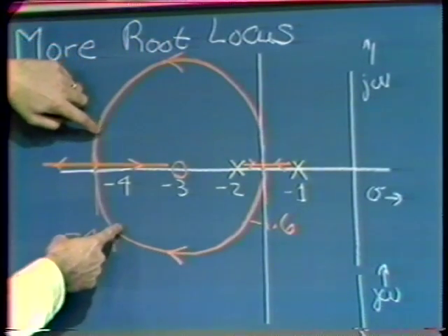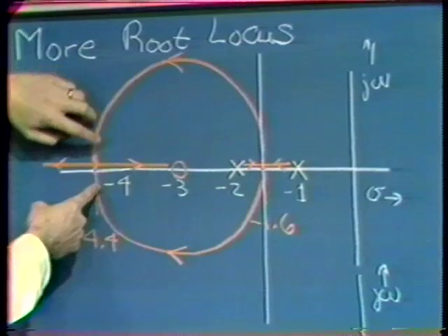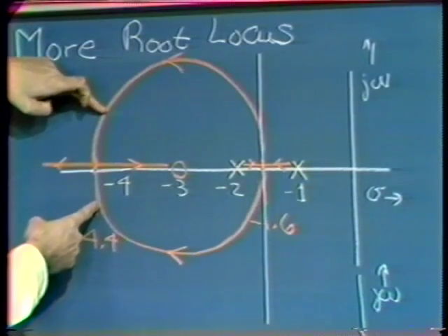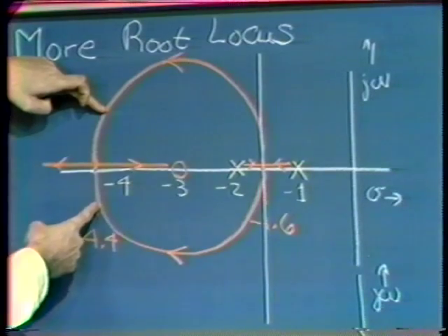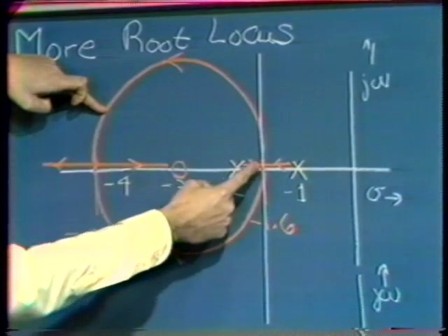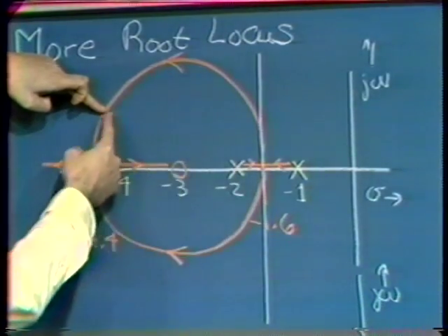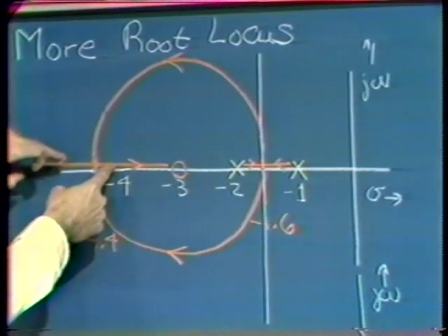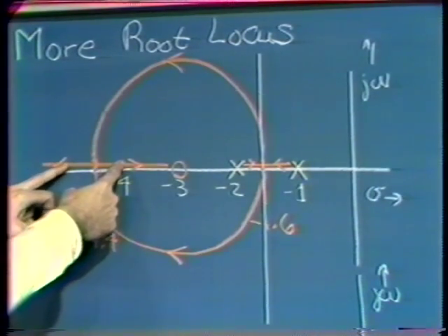Again, further increases in A naught, F naught actually further increase the damping of the pole pair. If we, for example, turned up A naught, F naught to this point, we'd have quite a high value for damping ratio, a damping ratio maybe of 0.8 or something like that. And still further increases in A naught, F naught result in two real axis poles.